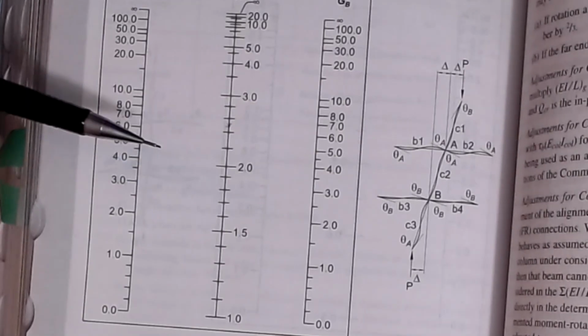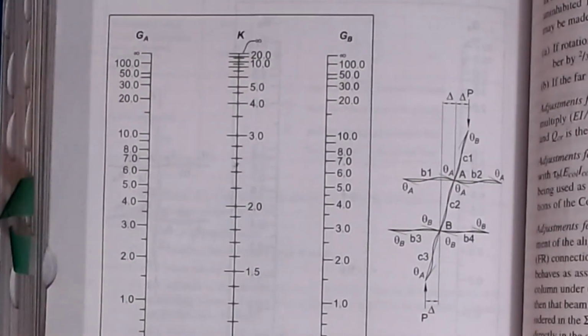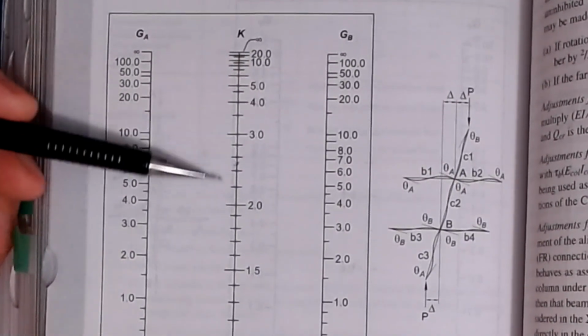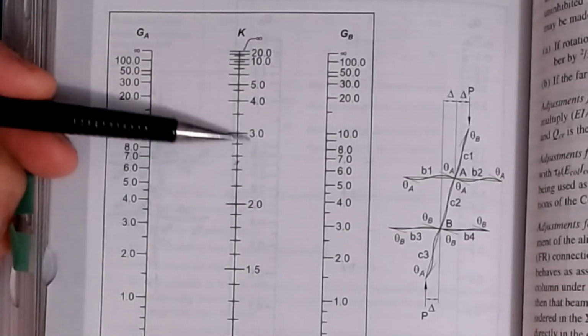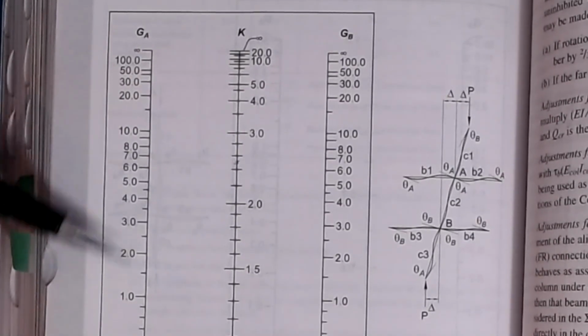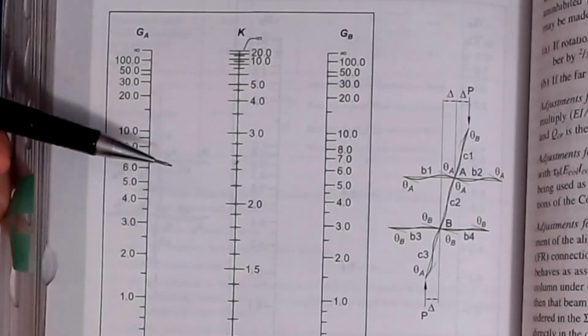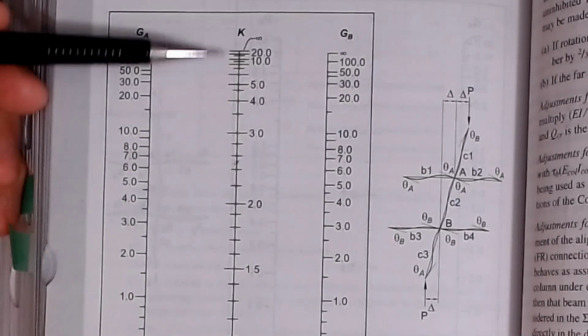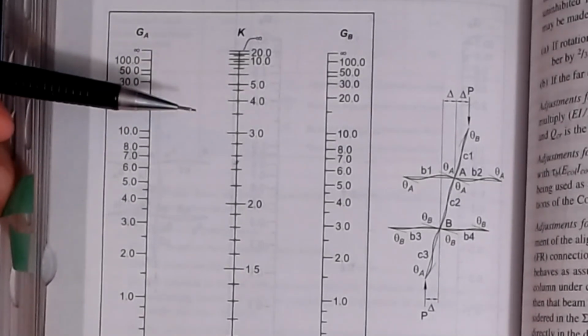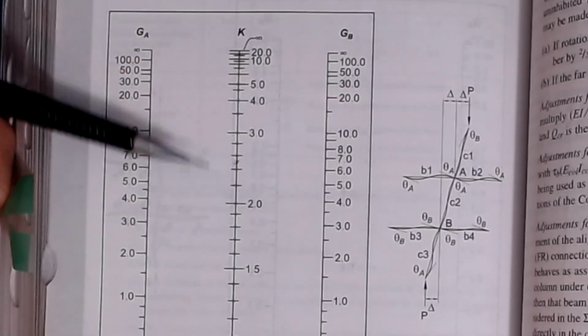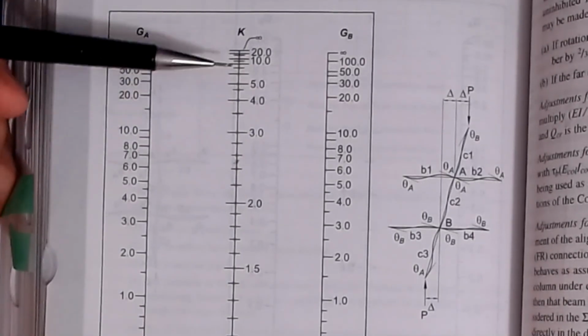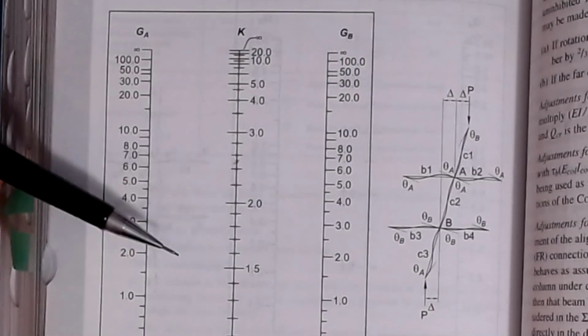For most normally framed structures, you generally wind up in this range of 1.5 to 3 for your moment frames, just for normal loads and normal arrangements, nothing out of the ordinary. Getting up into here, you have to start thinking about what to do with your geometry. Is there something else I can be doing differently with the framing to help with that monster K value?